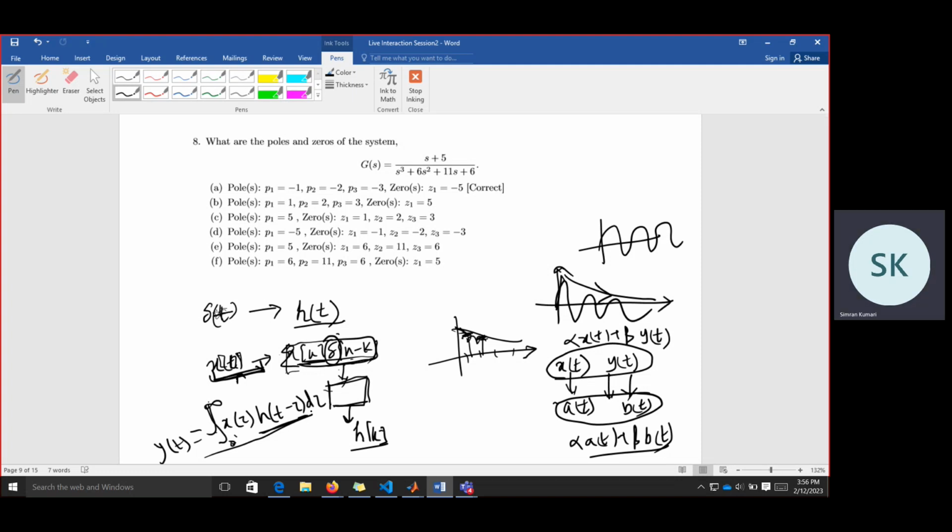Now this is computationally expensive, so we have the Laplace transform tool with us, and we try to utilize it. Instead of going through this lengthy procedure, we simplify things and just use the Laplace transform. So for a system, what we have defined is the Laplace transform of the output y(t), if this is the system which is given x(t) and the output is y(t), divided by the Laplace transform of x(t), with initial condition 0.